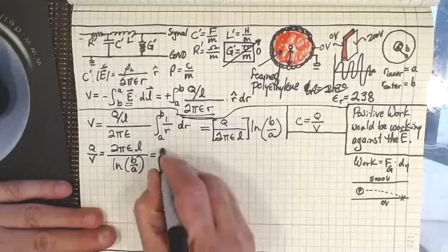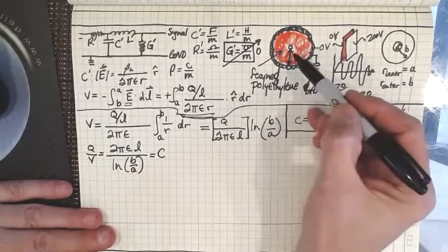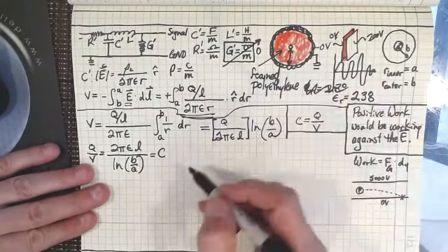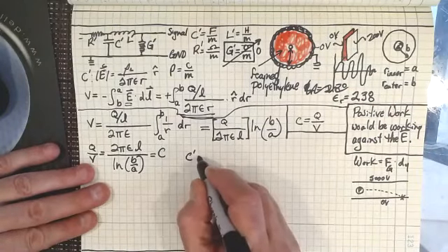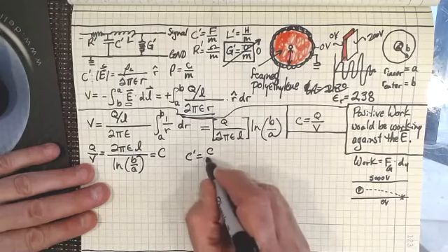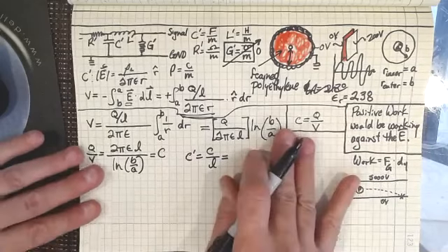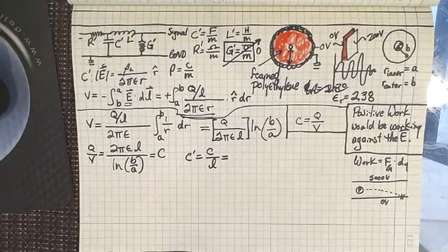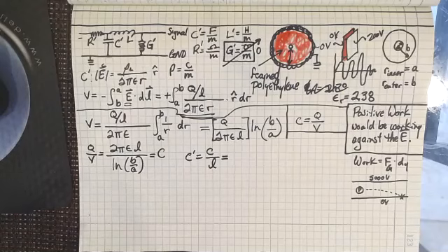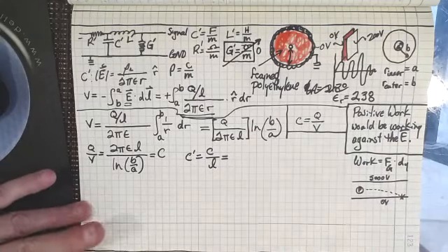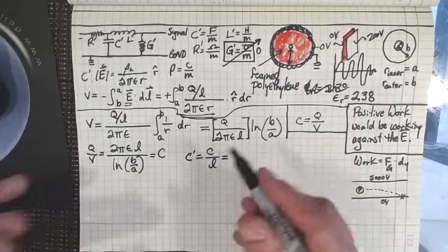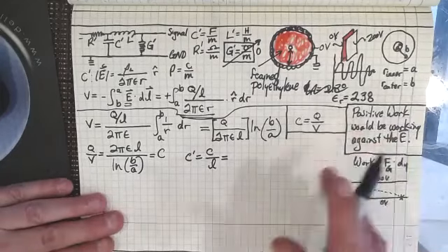So of course that equals capacitance, right? That's the capacitance for the whole line, but I don't want capacitance for the whole line. I want capacitance for the line divided by the length. I want capacitance per unit length of the line so that I can come up with an attenuation per meter. Then I could just multiply it by how many meters of line I've got, and I'll find out what the attenuation is at whatever frequency I'm broadcasting.